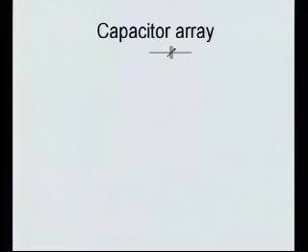Okay, so how do we do that variable capacitor? I just drew it like this, but that's not very helpful. One way to go about this in a more pure analog system is you put in what's called a varactor, which is often just a reverse bias diode, and you change the bias, and that changes the capacitance, and there you are. But that requires a nice, clean analog signal, and a clean analog signal normally means big capacitors, and that's off chip, no good. So I was trying to do it all digitally.